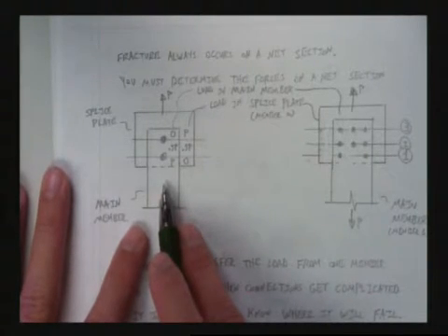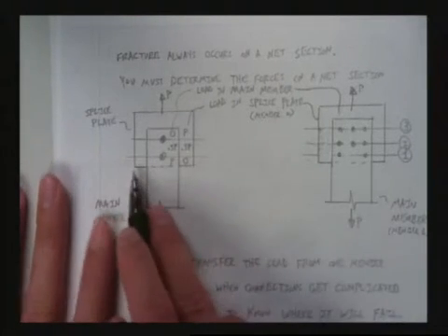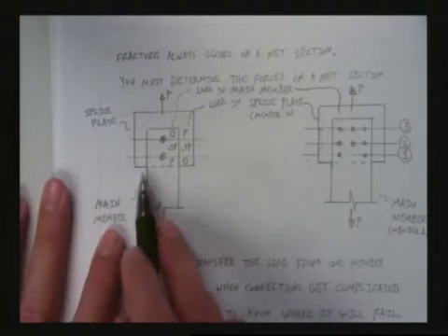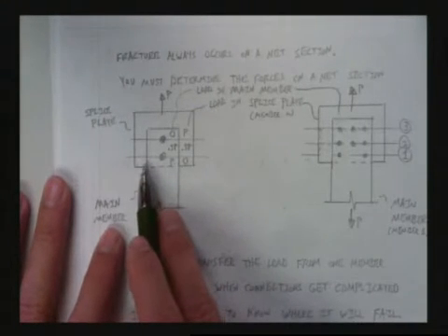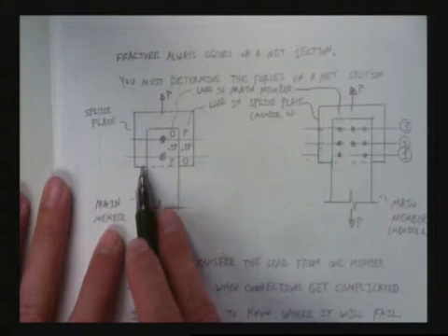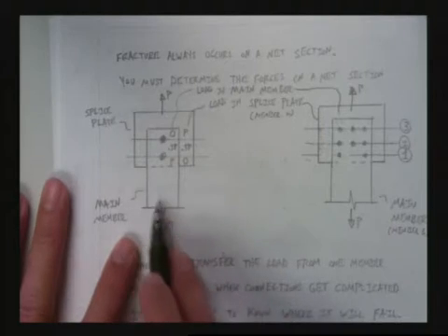Because in every single problem in this class, when we go to draw a failure mode, we have to draw a free body diagram of that failure. It's required. Okay, you have to draw where it's going to break. Some people don't really know where it's going to break, and that just shows that they don't really understand what they're doing. Okay, we're going to make sure you do. So let's just say the bottom member, I mean, this wouldn't have to be done this way, but to simplify things right now, let's just say the bottom member is really big and fat, all right? And we're just looking at what's going on in the top member.